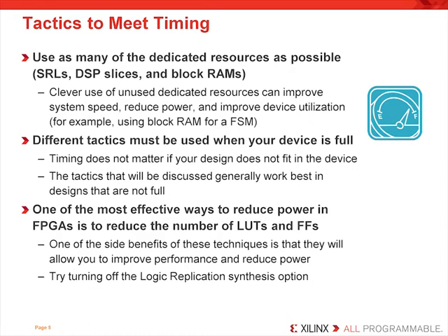The best solution is to shrink the register and LUT utilization of your design and to port all functionality to the dedicated hardware resources that you possibly can. Now, this may require the designer to employ some clever use of the unused dedicated resources, but the side benefit is that since the dedicated hardware is fixed in silicon, its timing should be faster than you could implement with equivalent logic, that is, with the slice resources.